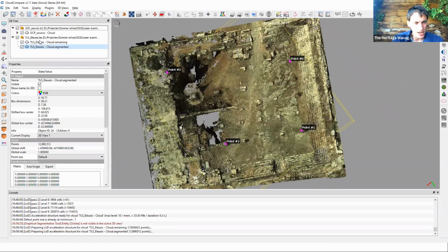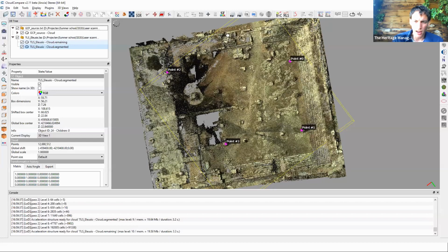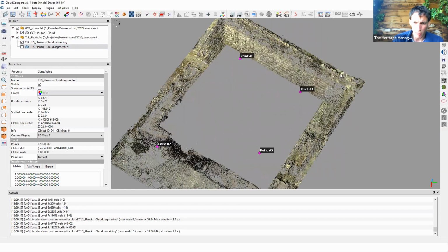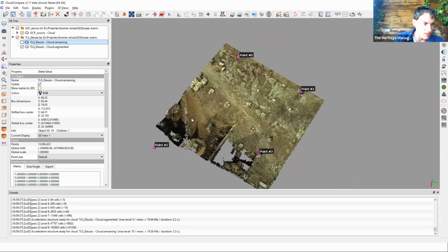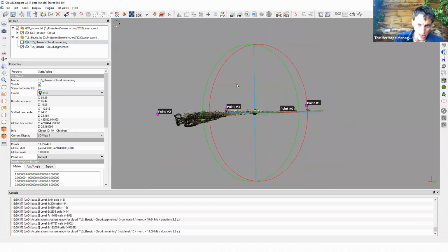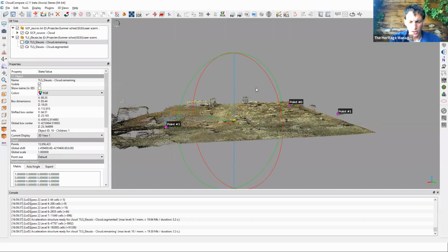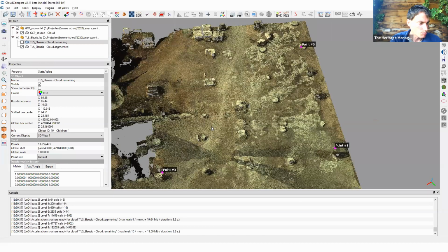And now you will see here 2 point clouds. The one that I want, so this is my segmented point cloud, and the points that I have removed out of my segmentation. So this is just everything that is outside. This is the part of the first segmentation, and this is part of the second segmentation, but that's all merged into the point cloud entitled cloud.remaining. And this is my final result. So this is quite useful for manual filtering, but also if you have a very large area covered by your point clouds, you can just take small samples of large point clouds.